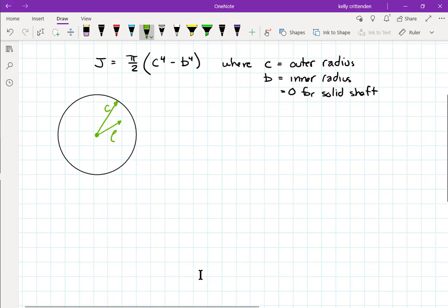So remember when we did axial deformation, we had delta, the change in length, equal P times L, or sometimes I think we actually used the F here, F times L over E times A. We had this relationship to calculate axial changes in length. Well, there's one for torsion that's very similar, theta, so this is angle of twist.